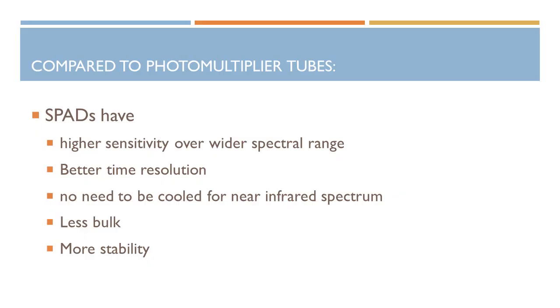The dimensions of the diode are also much less bulky, making an assembly of large arrays for detectors more feasible. Photomultiplier tubes are also more sensitive to electromagnetic disturbances and mechanical vibrations, and so making the device more stable requires more internal mechanical structures and therefore raises the price.